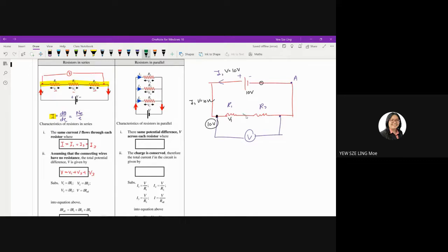And when it reaches this point, this I is now just moving with V. Maybe the energy is now 6 volt after it passes through R1. So it experienced a potential drop of 4 volt. Why? Because this 4 volt is being used to overcome the resistance from your resistor 1. And as it keeps moving, after it passes through R2, what happened? Now your V becomes 0.